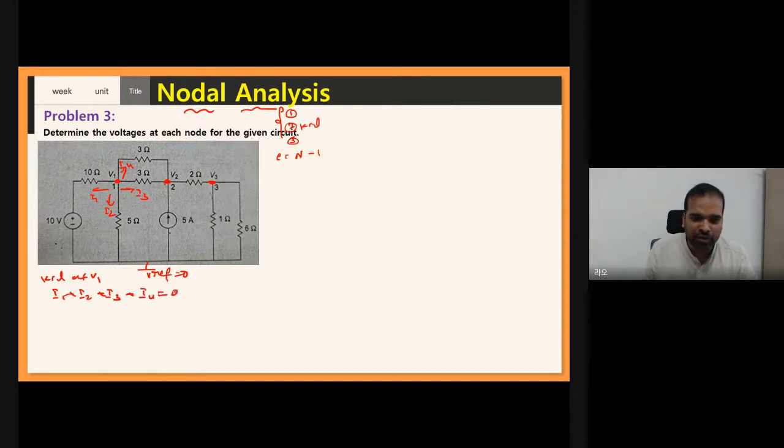Now you know, as per Ohm's law, I equal to V by R. You need to find the voltages in the numerator for I1, I2, I3, I4. Now see, I1 means what? I already explained how to find I1. So I1 equal to what? On one terminal V1 is connected, with reference to 0, minus 0, and on the other terminal the 10 volt source is connected, so minus 10, divided by the resistance value here,